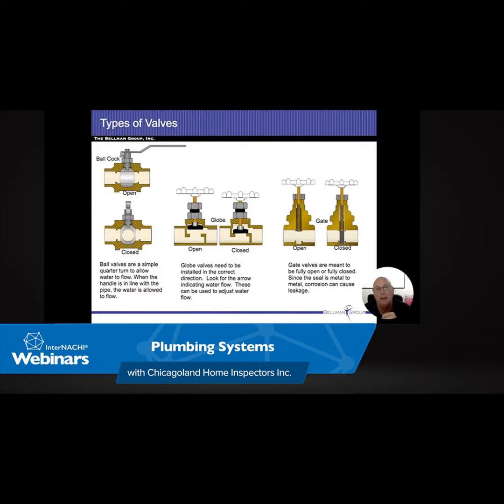All right. I do want you to know that ejector pits need to be vented, they need to be sealed, and they need to go into the raw sewage lines. Where some pumps, they don't. Some pumps don't need to be sealed, unless it's a radon system. We don't necessarily have to seal them up, but they're going to go either outside on the surface.